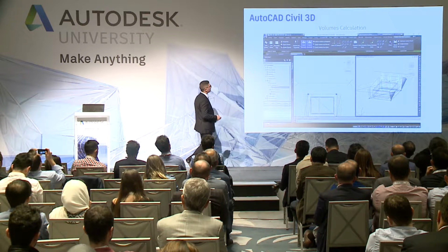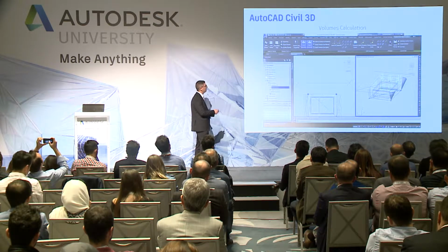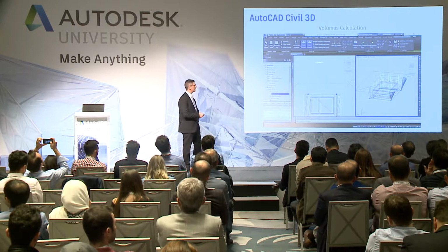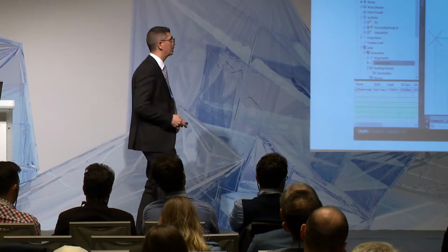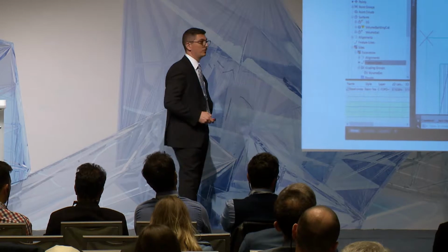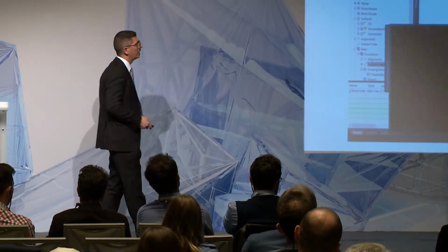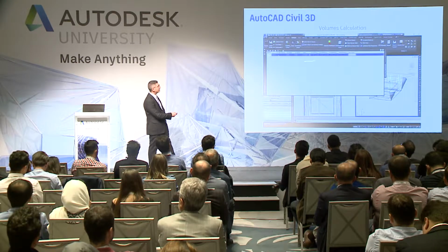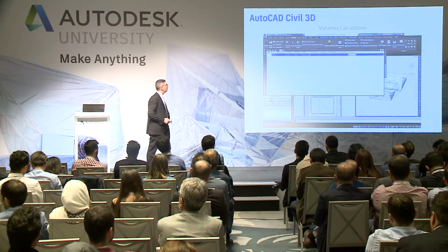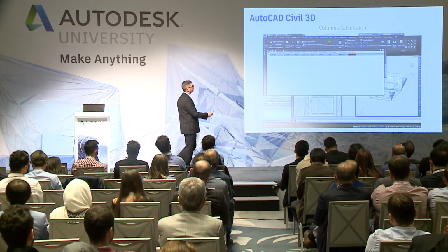And if you look here on the surface, we have a yellow question mark. That means, look, your model is not updated. Then please click on update. I go to the volume dashboard, and I can click this button, update, and I immediately have the update of my model, OK?